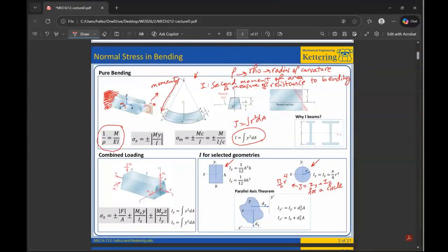All right. So this gives us a measure of the radius of curvature, but what about stress? Stress is this equation from this point on. If I ask you what is the normal stress equation due to bending, simply say plus minus Mc over I. Let's just look at this. The textbook refers to y in this particular case. What if the coordinate system is picked differently? Then it's different. To make it easier, let's just simply call it plus minus Mc over I.